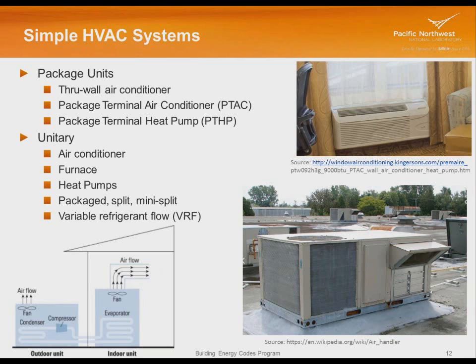They have an outside portion where they reject the heat outside, or in a heat pump situation, they reject cold outside and heat inside the building. So they produce that transfer of energy. Unitary air conditioners are typically a little bit bigger in size. And a unitary air conditioner can either be in a single package, so here's another use of the word package, or they can be a split system.